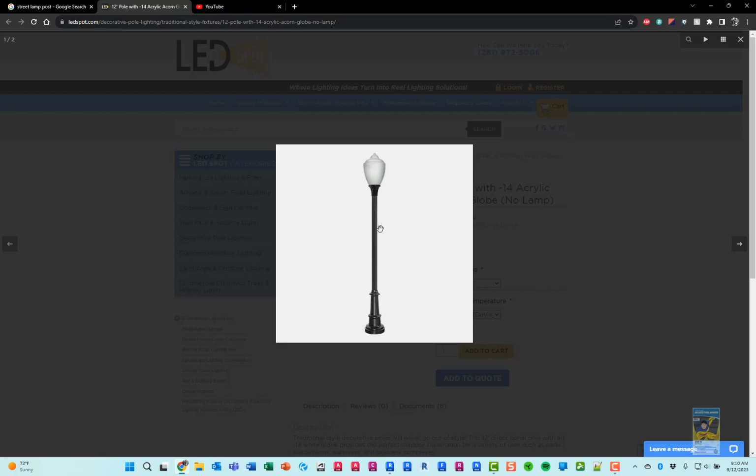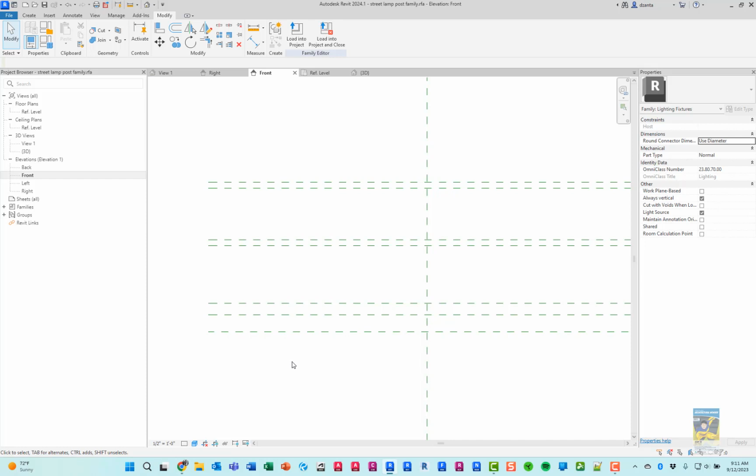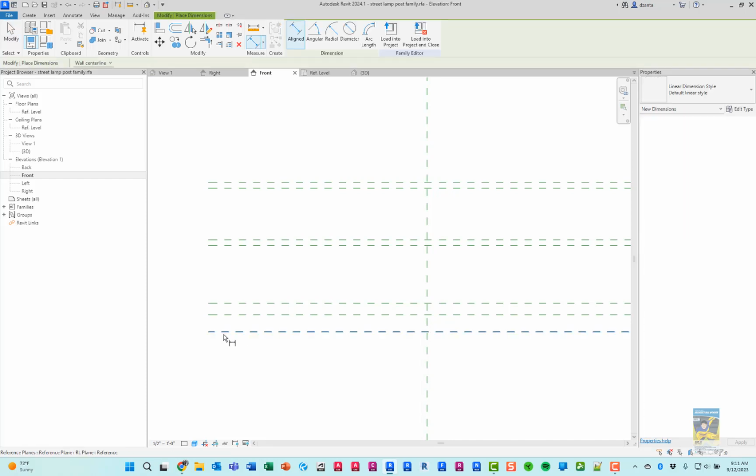Now, when we're doing the design of this, we have to ask whether this information here, here, here is adjustable, and here, if it's adjustable in height. We're going to make all of this fixed to make life easy. But you can parameterize everything, really, honestly. But for the sake of ease, I'm going to put in the dimension and lock these dimensions. That way, this doesn't change.